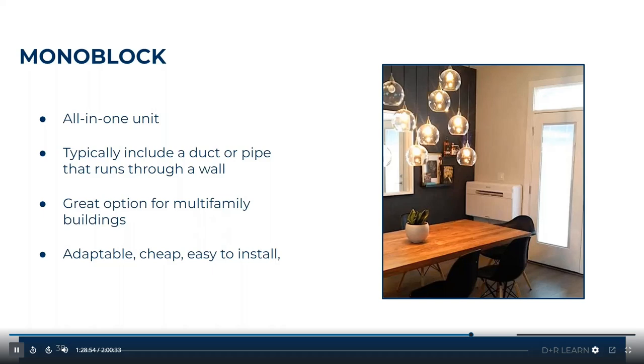So whether that's your front door opening and closing or a window being popped open here and there, that is typically the only way you're going to get a good fresh air changeover within a split system. But when you have a bigger system, or more on a commercial level, your air handling system is typically regulated to be open at 10% minimum to provide that fresh air introduction into that space.